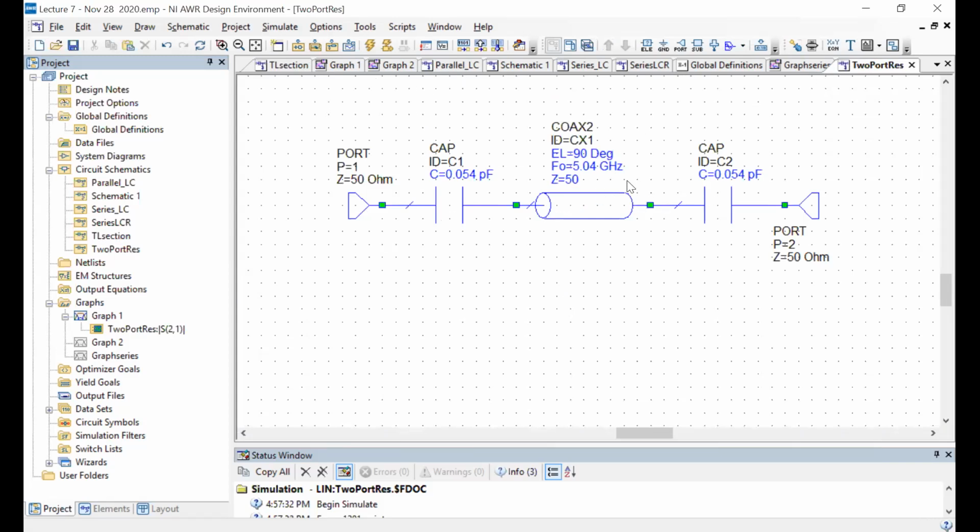In fact, here seems to be a significant reduction, but that's, again, if you remember, it all depends on the ratio of the capacitance, which is representing the equivalent circuit for this part. And in fact, the equivalent circuit for this looks like this. So the middle part can be replaced by a parallel LC resonator, and the two coupling capacitors show up in the same way. So in the effective model now, these two capacitors come in parallel, so that there are now two capacitors, both of them add, so overall frequency reduction is even more.